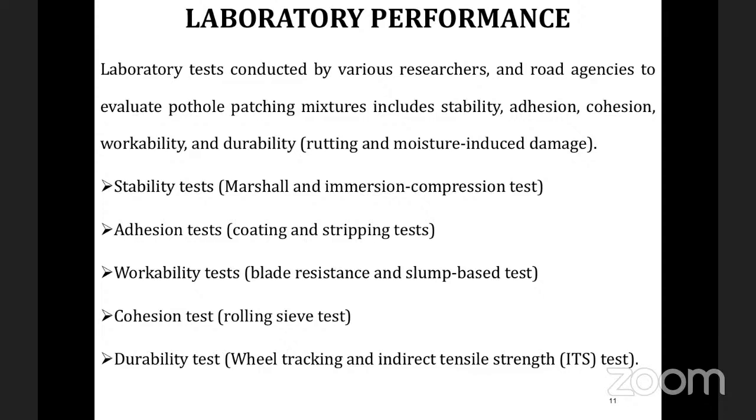Next comes the cohesion. For cohesion, they have given a simple test, that is the rolling sieve test. That is also given in the Indian code, that is IRC. And the last one, which we have to focus on, is the durability. For rutting, we can go for the wheel tracking device. That is the number of passes, and what the rut depth is for the number of passes.